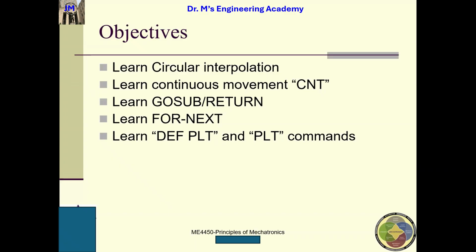Palletizing means that I want to move all these workpieces or items from this grid to another grid. The other grid might look this way or might look different. So I need to define the palette. I need to use the palette to automate the movement from grid 1 to grid 2. Okay, so this is called palletizing. You understand, guys? Okay, good. We will have a lot of fun using palletizing.